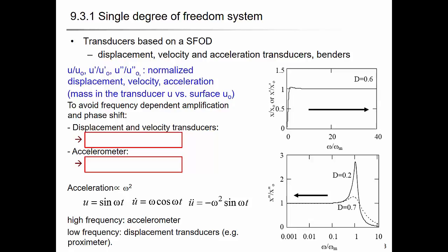Let's talk about the transducers. So we use an accelerometer. I think you've done that already with the FFRC. And in the field, people can use the geophone to measure the low frequency velocity of the ground motion. And LVDT, right, for displacement measurement. And pressure transducer and load cell, right, strain gauge. There are lots of sensors applied in soil mechanics and geotechnical engineering. And here we will talk only about the transducers that can capture the dynamic response.